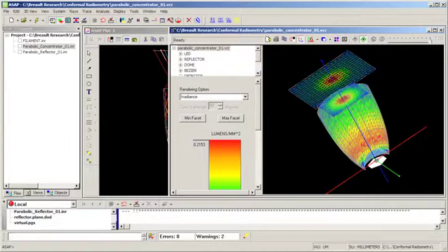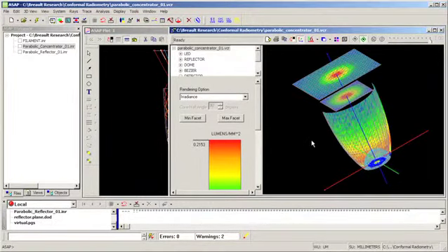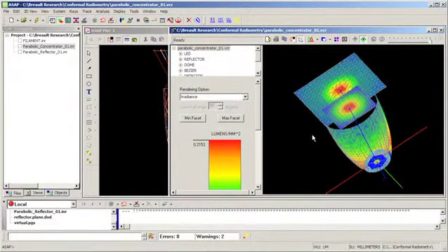So we've now mapped the radiometric information that we calculated for this example into our 3D viewer. And one thing we didn't mention was that we added the bin keyword modifier, in this case, to virtually every surface in the system. And so that information has been plotted for all the surfaces that we see. Now we mentioned earlier that we added two detector surfaces, which in this case were defined to be transparent and therefore have no effect on the resulting ray trace. And yet we see that we have correctly calculated the irradiance at each of these two surfaces.